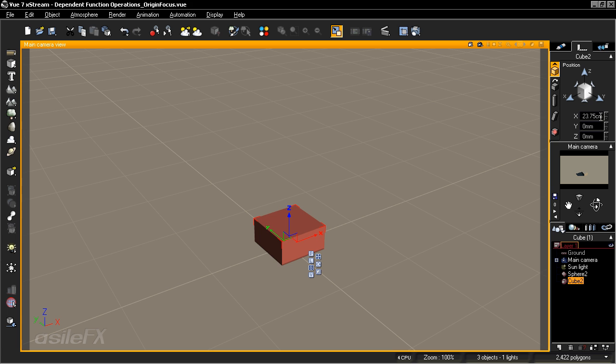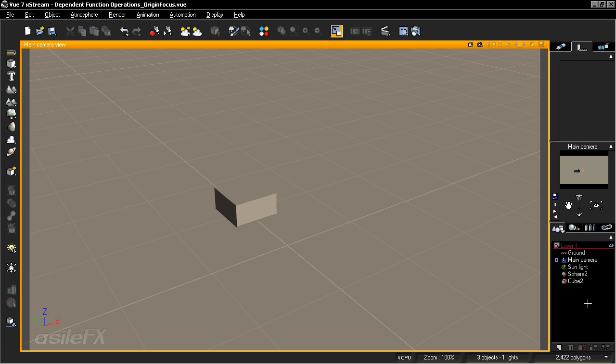So let's take a look at how that offset is going to work. Our cube, we're going to set back to 0, which is also going to take our sphere and set it back to 0. But what I want is to have our cube 10 meters on the y. So we'll type in 10 meters on the y. But what that's actually going to do is modify our sphere. Well, we want this to be our starting point and a non-controlling value. So in other words, we're changing the origin of our cube without it affecting the sphere.